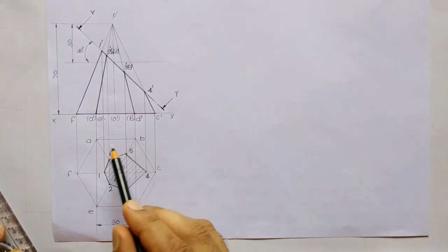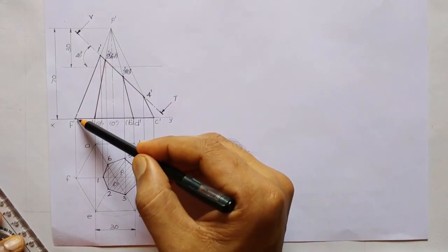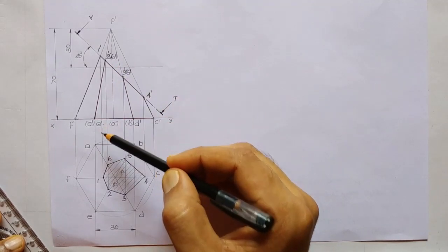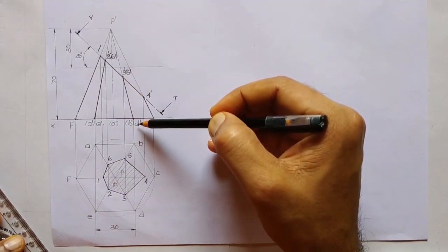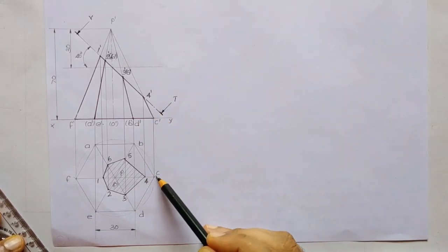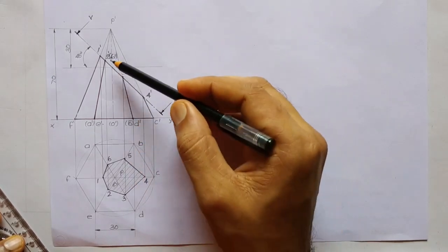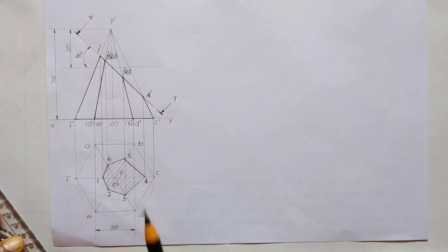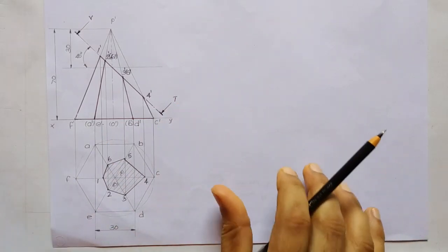And we shall draw the remaining regions in the top view also. So here 1' f' is remaining, so this is 1f, 2e is remaining, 3d is remaining, 4' c', so 4c is remaining, 5b is remaining, 6' a', so 6a is remaining, and the base is completely remaining. We shall draw each of them using thick lines.